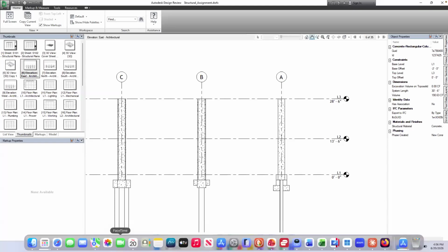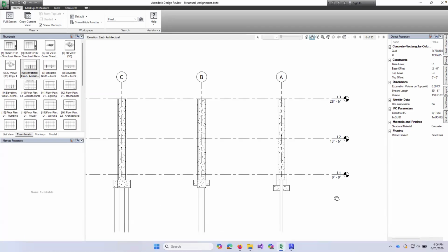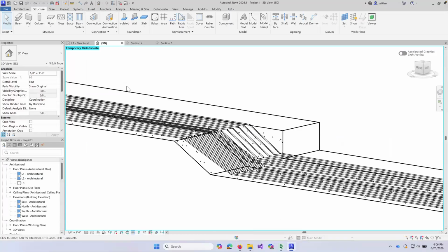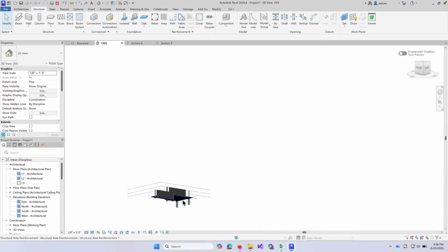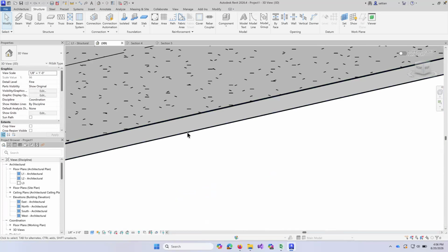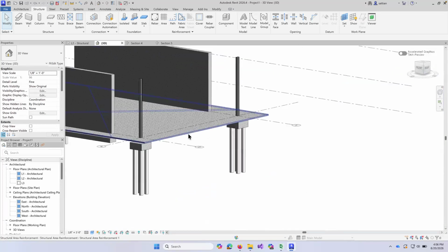So if I want to create an object that is a custom slab edge that I want to use on my slab, first of all, on my slab, if I wanted to create a slab edge, so let's reset this 3D view. Click on that and reset temporary hide. We see everything. Let's say that we go to shaded again. So there's my slab, right?